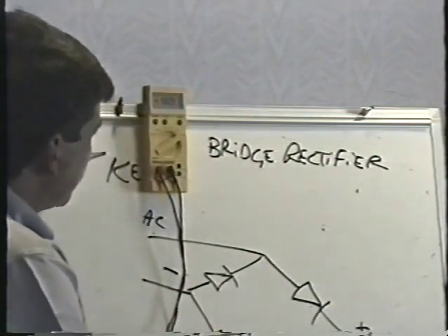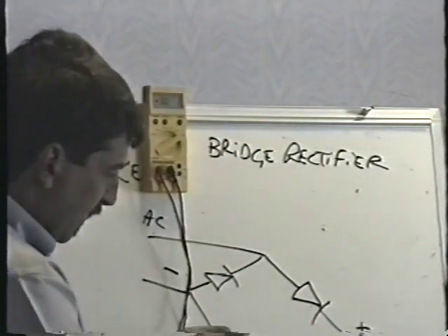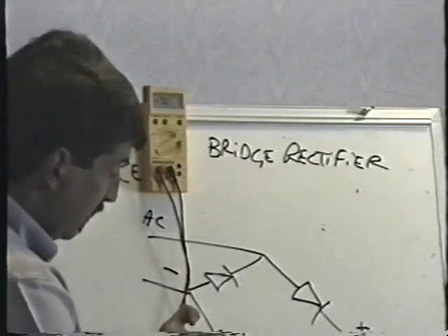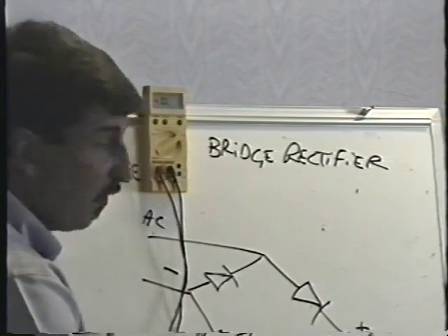See, this one's really giving me some weird readings. Now I got 0.4 on that one. That's really strange. That's pretty darn low. I get an open in the other direction. I get an open reading there. Open reading both ways on that one.